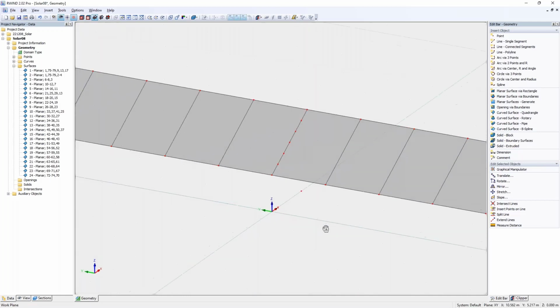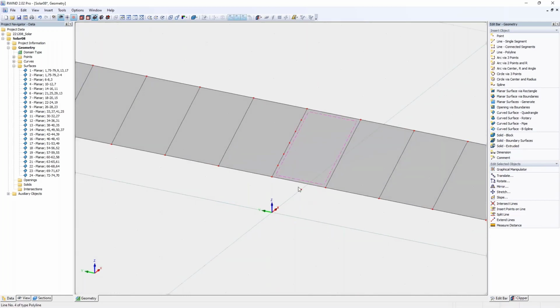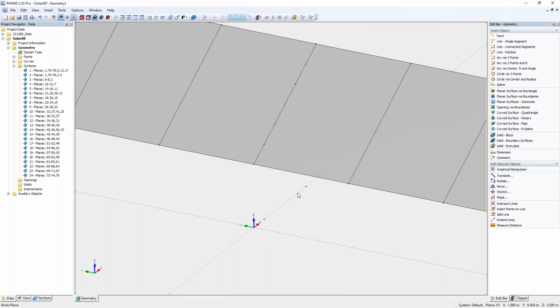You can imagine there are smarter or even faster ways, but I'm usually used to doing some quick geometric stuff. And then I want to have quite thick columns, just for an example, 20 times 20 centimeter columns. I will press Ctrl C and Ctrl V on my keyboard, which is most likely quicker than the translate, but the translate offers some more options. But if you just want to quickly copy some nodes, like me, I want to copy it in this direction, then I can do this because I want to create a rectangle.